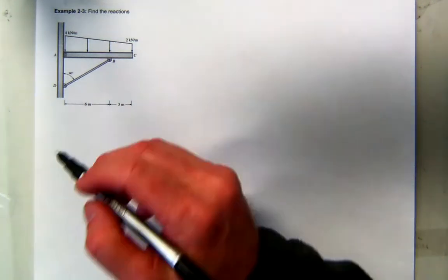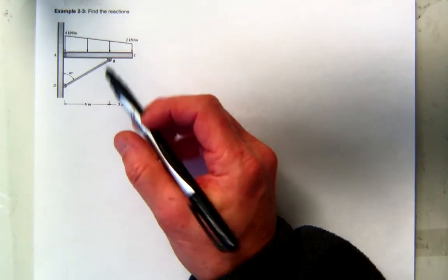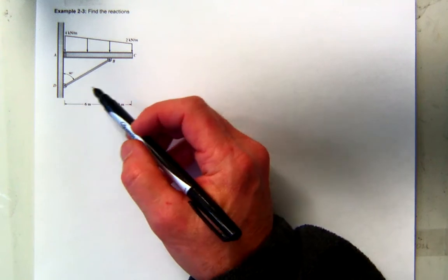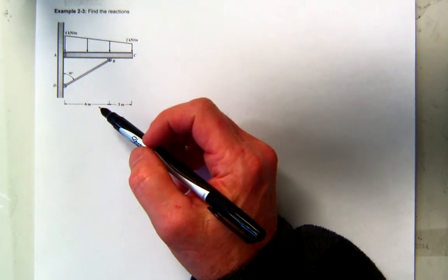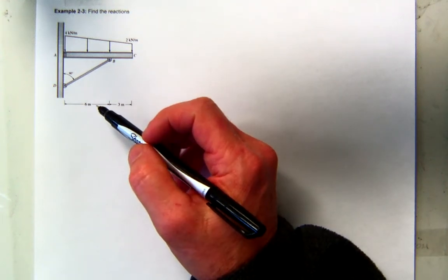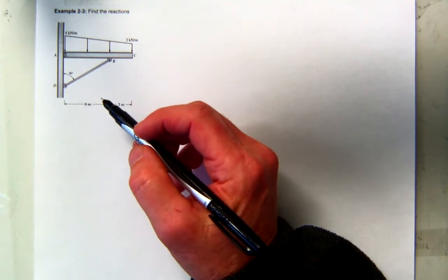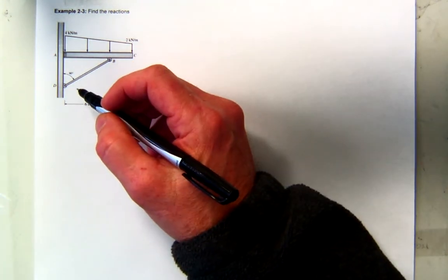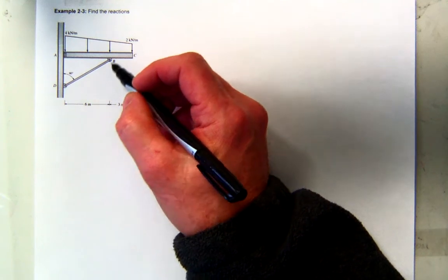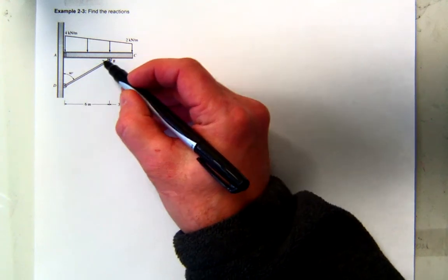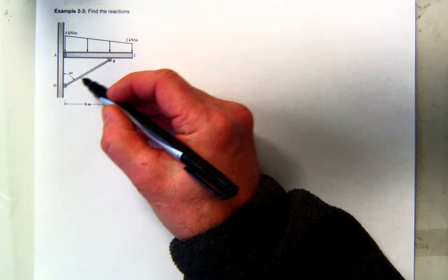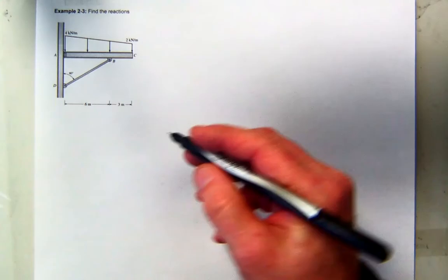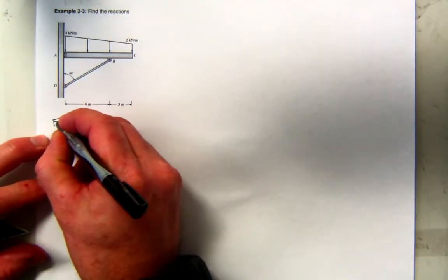And when we do that, think about section DB. If I did pull that apart, what would it look like? Well, it's pinned at both ends. Are there any forces applied to it externally? No. That's something we talked about earlier. What's that called? That's a 2-force member. So it's not 2 unknowns. It's only 1. I don't know the magnitude, but I definitely know the direction. It's on this line of action from B to D. Okay? So when I draw my free body diagram...